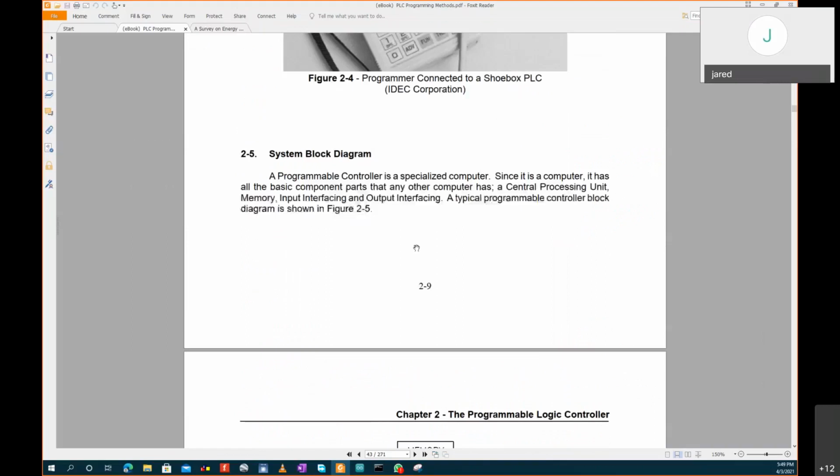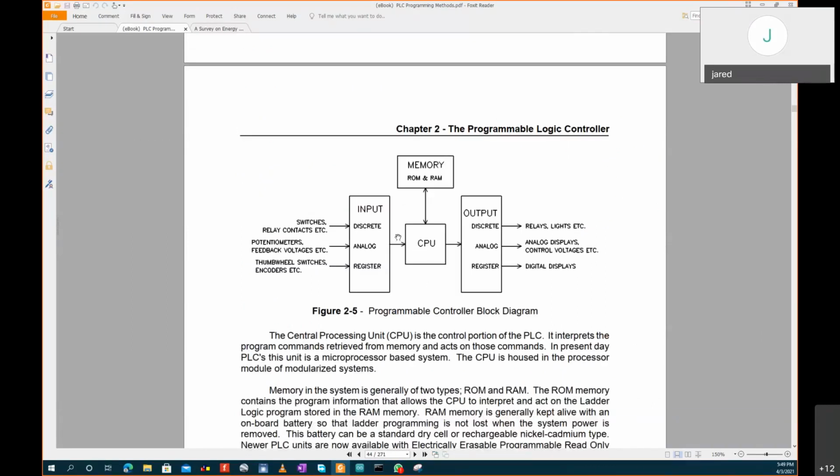So this is just a logic block diagram. If I tell you maybe draw for me a logical presentation block diagram of a PLC, this is what I expect you to do. If you get this question, you need to know the discrete inputs, analog inputs, and the registers. Then PLCs have a ROM, they have a RAM, they have a flash memory, they have EEPROM, and SRAM. It's the same way as a computer.